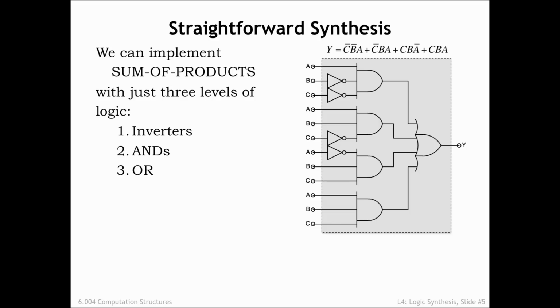We use inverters to perform the necessary Boolean NOT operations. In a sum of products equation, the inverters are operating on particular input values, in this case A, B, and C. To keep the schematic easy to read, we've used a separate inverter for each of the 4 NOT operations in the Boolean equation. But in real life, we might invert the C input once to produce a not C signal, and then use that signal whenever a not C value is needed.